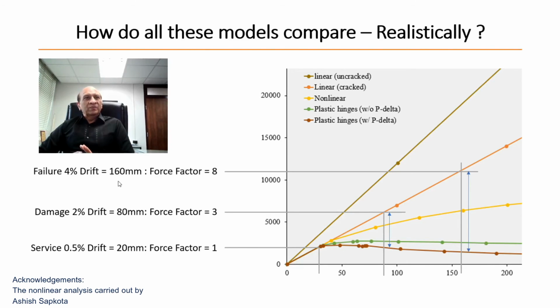So the building codes and engineers working on the design for seismic effects are aware of these reductions, and they are incorporated indirectly in some of the factors. But it's important to see that the linear response has its limitations, and it cannot really predict the actual response even for a simple frame like we have considered here.